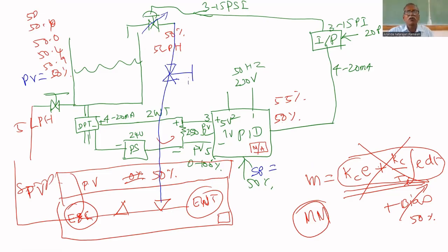First, to put the controller in manual mode, give controller output 50%, allow the level to settle. Let us assume that it is settled at 50%. You cannot expect that if you give 50%, you get a 50% settlement. You cannot design such a process in practice. Theoretically, you can say 50% open, 50% level. There, if you give 30%, it may settle at 50%. I understand this. That's why somewhere it is settled, so you cannot expect 50-50. For convenience, I am telling all these things, 50-50 and all. Okay. So you gave 50%, it is settled at 50%, let us assume.